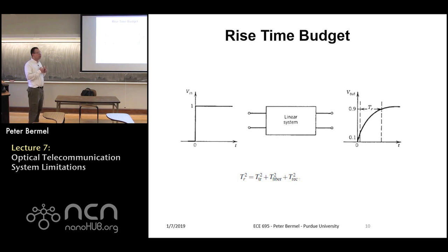And then there's another factor that's very important, which is how quickly your signal can rise or fall, right? All of you know about RC circuits, so I don't have to explain that. But the point about this system is that there are several sources of effective capacitance in the system. One is associated with the transmitter, right?